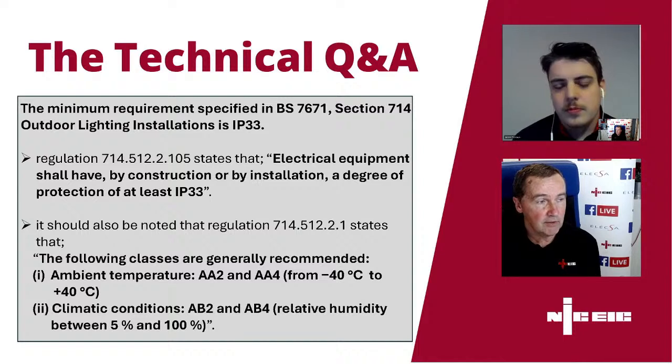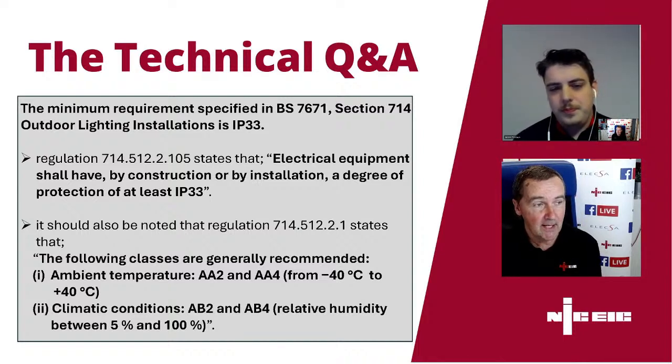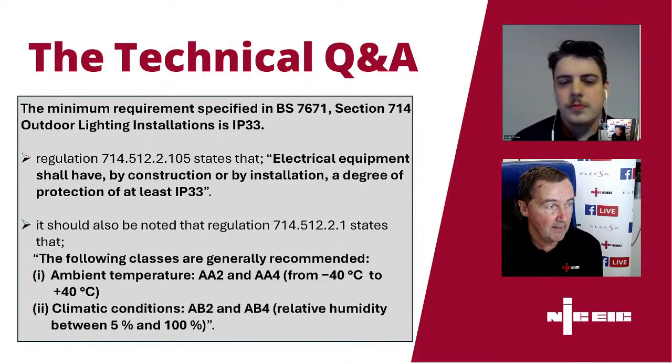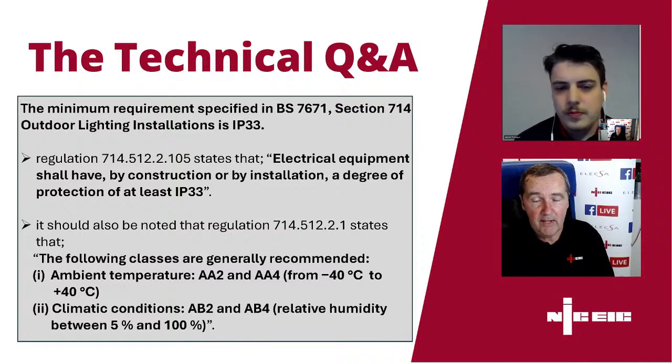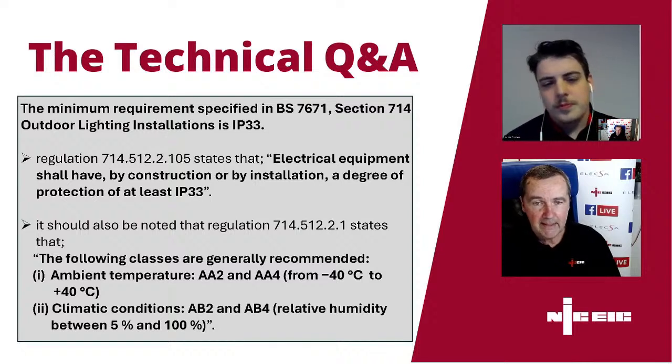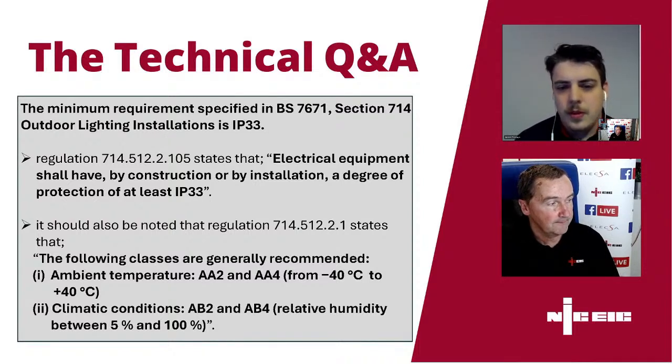Definitely, I would suggest record the fact that you did contact the DNO and they said because it was remote they wouldn't get it any lower, and then you've done everything reasonably practical. So yeah, record those things, and you definitely want to record the value, because at a later date, whenever you're perhaps doing some further additions and alterations there, or you're just doing a condition report, you'd want to check to see that it was a stable value greater than 0.35 and not something that was incrementally increasing from 0.35.